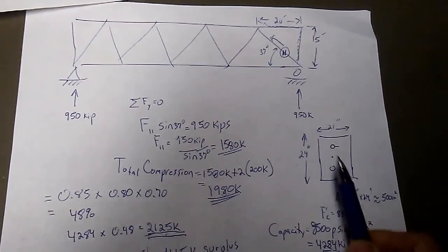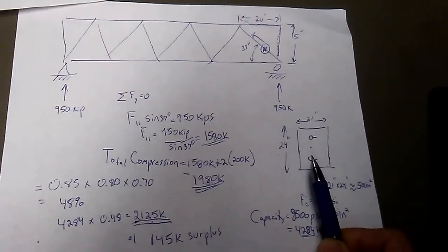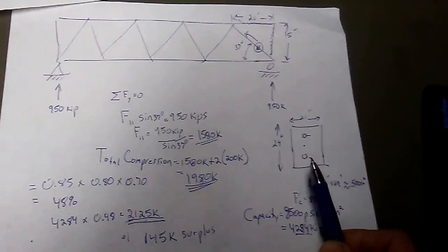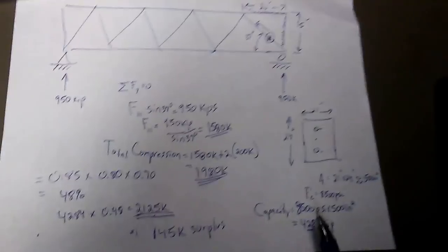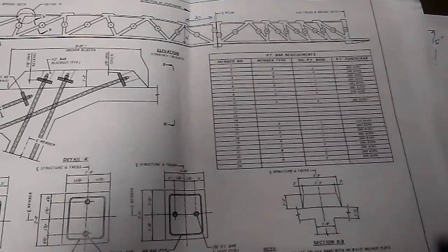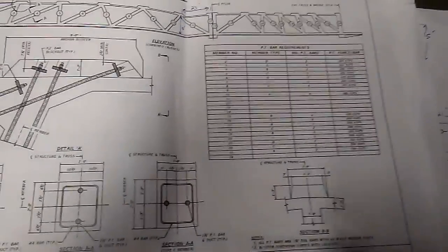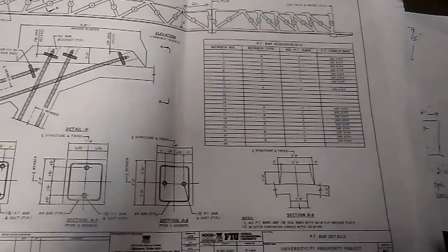So I think what happened, and I'm proving it here, is that the contractor in his post-tensioning exceeded this 200 kip tension that the drawings were showing, at least the preliminary drawings show. Again, I just want to clarify, the drawings I'm basing my findings on are the ones on the internet. They're not the drawings that were actually used in construction of the bridge. They're preliminary drawings submitted in the bid proposal by the design build company.